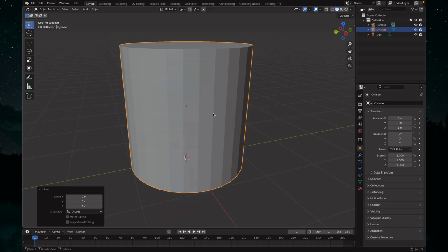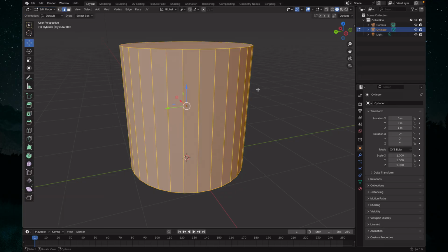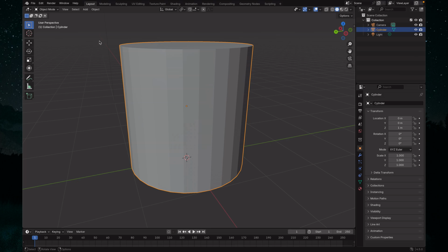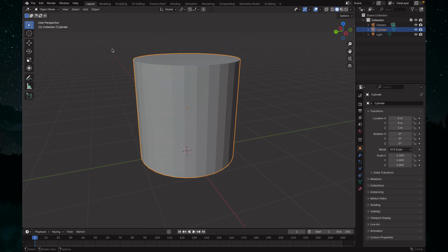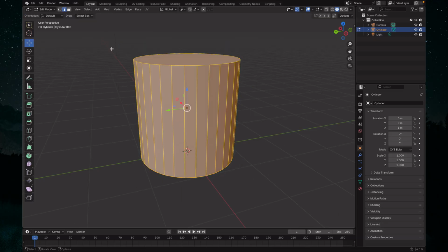So right now, the mode that we are in is called object mode. Now, to do some editing, we have to be in the edit mode. So if we go to the top left of our Blender and click on the object mode, there are other options here. We are going to select edit mode, and we are here in the edit mode. To go back, Control Z. Another way to do it is clicking the Tab key on your keyboard. If we click the Tab key, you can see that it has switched us to the edit mode.